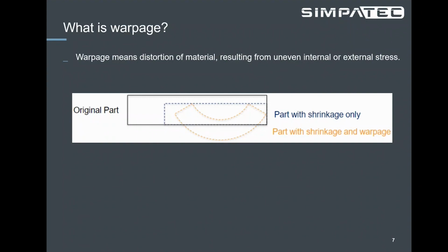One point is when we are talking about the displacement of the part, typically people are always talking about things such as shrinkage and warpage. The intention is simply to understand that when we are talking about warpage, we are just talking about shrinkage that has a non-uniform distribution. If you had a uniform distribution of shrinkage, then we wouldn't have any kind of warpage in our system.